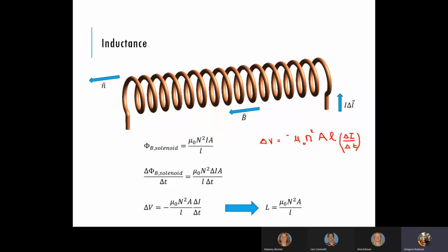Now, usually, in practical purposes, what happens is you still get an increase of current through the computer. The issue is that instead of getting this huge spike, it levels it out a little bit more. So it doesn't stop it from getting all the way to your computer. What it does is it tries to level it out, instead of a rapid jump, it'll clip it.